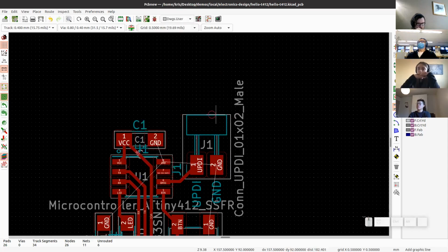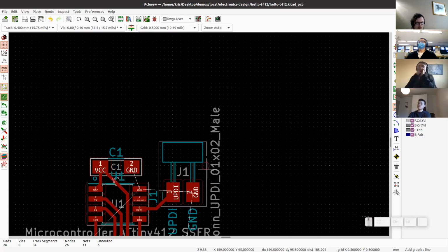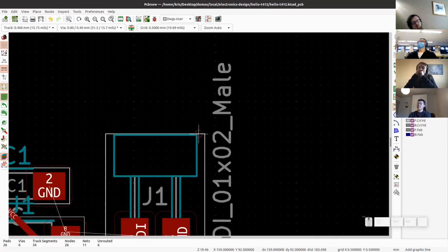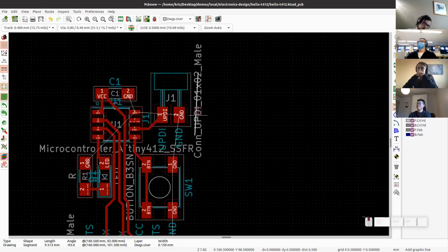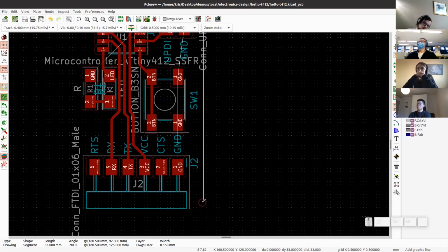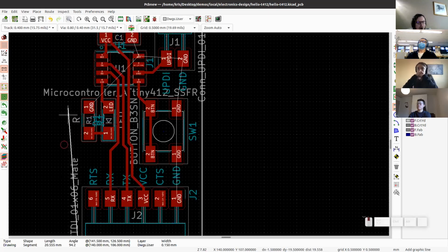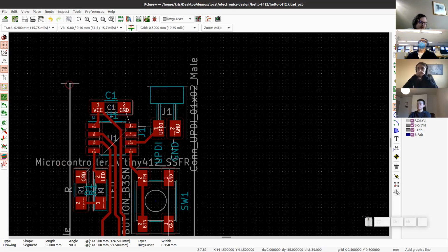It's going to allow you to orient yourself and figure out the size of the board in terms of millimeters more easily. So I'm going to just put a millimeter offset from here, start drawing downwards. And then I'm going to put one line here and around the FTDI like this. Like so.